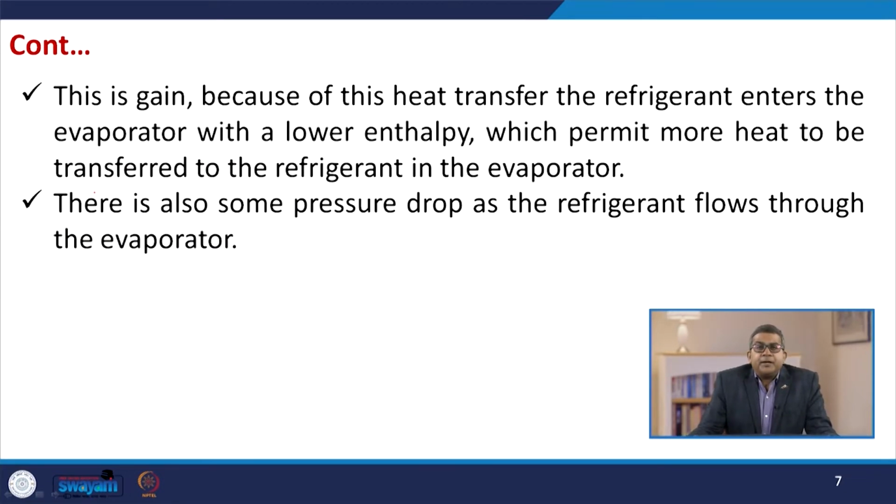Now this is a gain because of this heat transfer. The refrigerant enters the evaporator with a lower enthalpy, which permits more heat to be transferred to the refrigerant in the evaporator. So that's why this is a gain, and the efficiency of your refrigeration cycle can be improved.